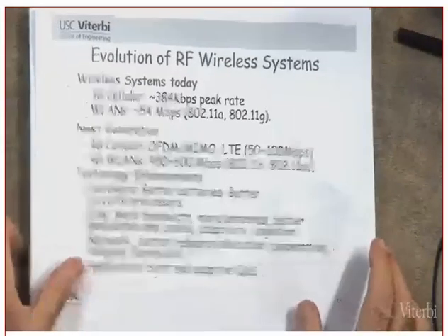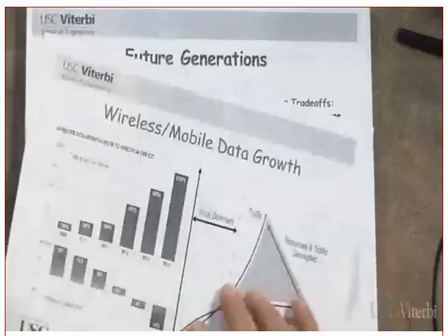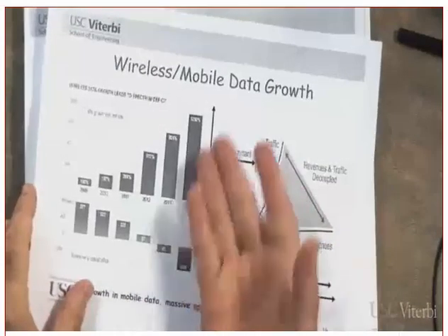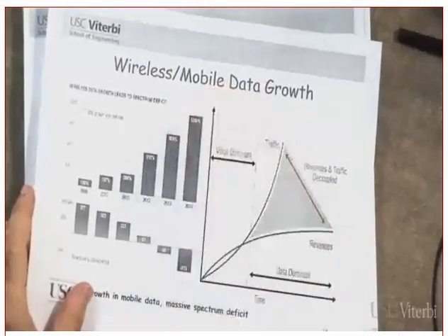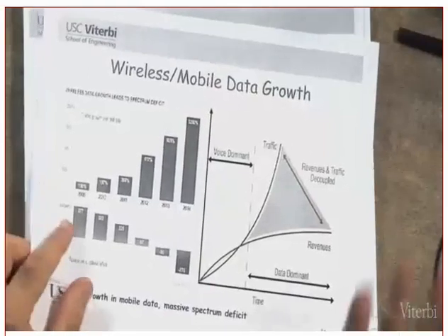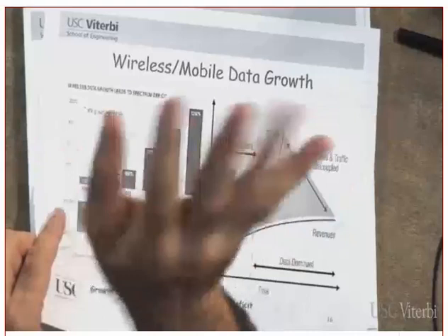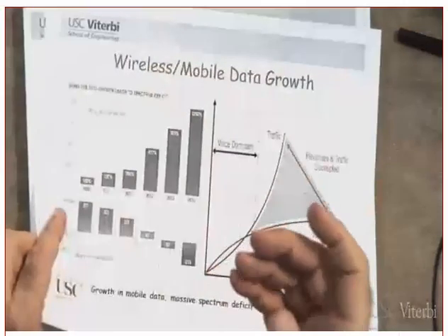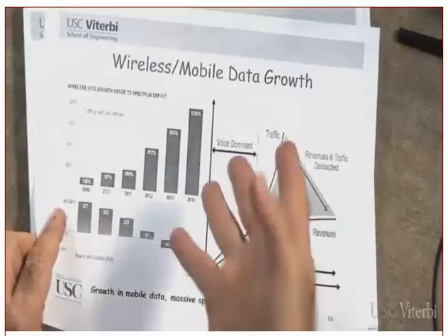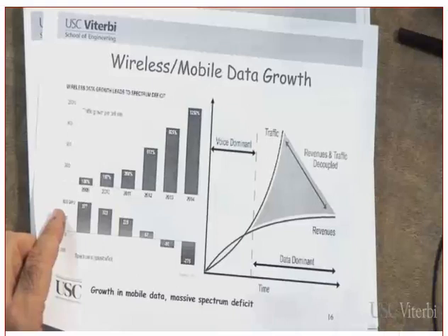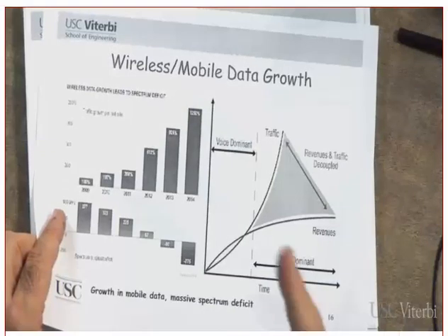Okay, good. Now, some trading, this is the growth. Most of the applications for wireless are now based on data. It's overcoming the voice. The problem with that is that data is bandwidth hungry, whereas voice is not. Anybody know how much each mobile voice call takes? How many bits per second? 8 kilobits per second, compressed voice. Is that high or low? Relatively low, for every phone call.